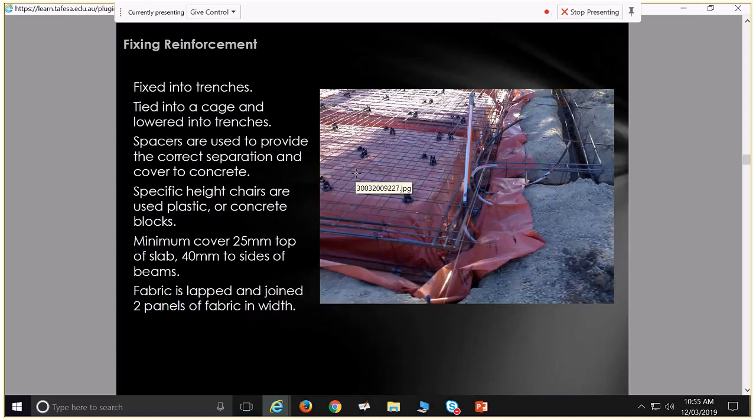But the people who are laying all this, doing all your formwork, etc., should also be checking that. Those sorts of things should be checked several times. They might want to come along with a concrete rake, which is a big flat thing, and just smooth off sections to get stuff right. So I imagine it's like trades checking each other. Yeah, we'll have several different trades that rely on, or check, the work of other trades as they move through.